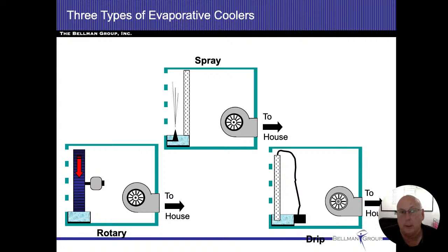So it's hard for us Northerners to understand this, but these evaporative coolers run with high flow air and big ductwork. You actually keep your windows open when you're doing this. You blow the humidity in the house. That moisture evaporates because of the very dry climate that they live in. And as it evaporates, it absorbs the heat of all the objects in the house, including the human beings it touches. And they actually work fantastic. Everybody that has them says that they're marvelous, all right?